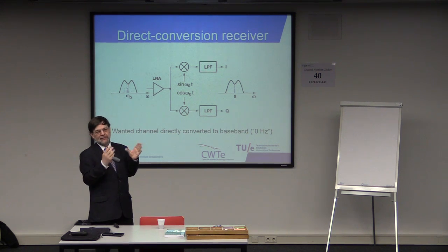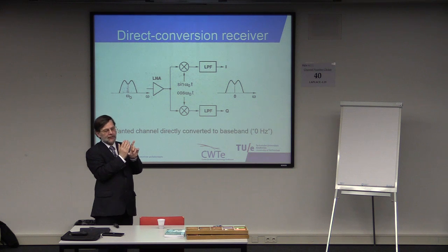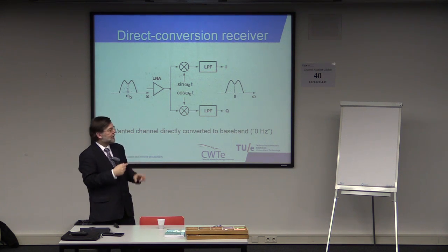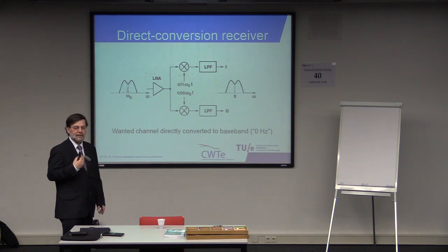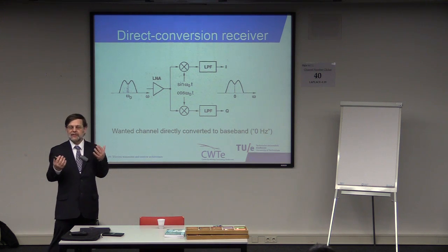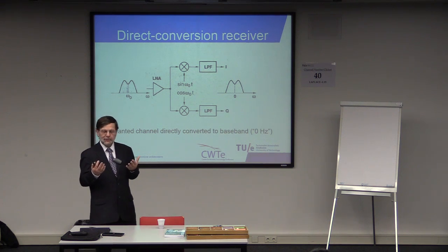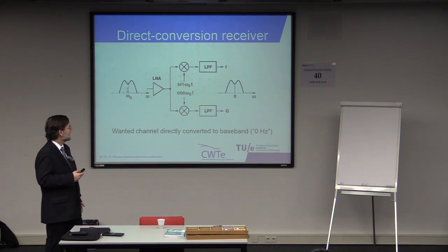And in 0IF, my interferer is myself, but now I can distinguish whether the intermediate frequency of my input signal is positive or negative by just observing whether I'm rotating my complex signal in a clockwise or counterclockwise way. And that's nice because now 0IF actually works. Now I can even use 0IF for signals for which the negative frequency part of the spectrum and the positive frequency part of the spectrum that's being transmitted are different, because I can distinguish them in the I and Q domain.